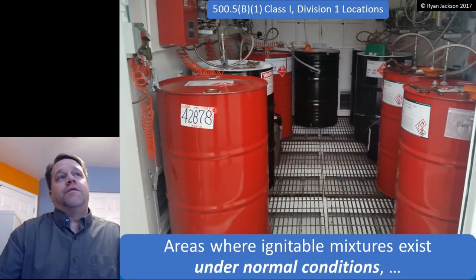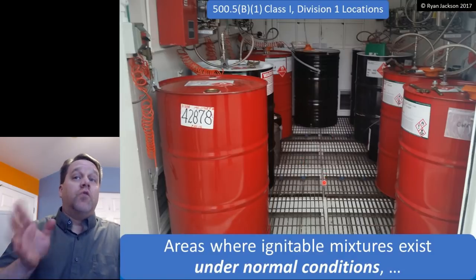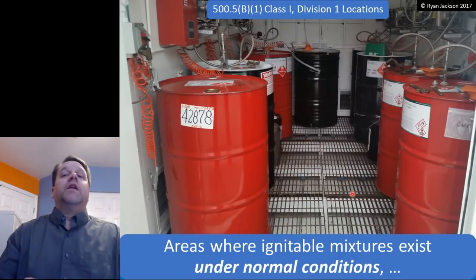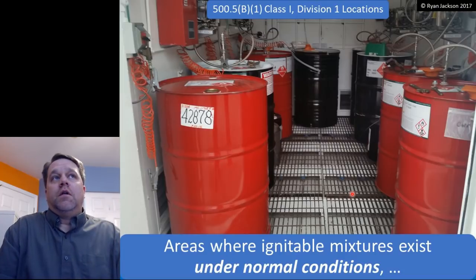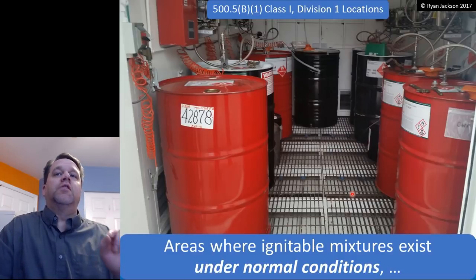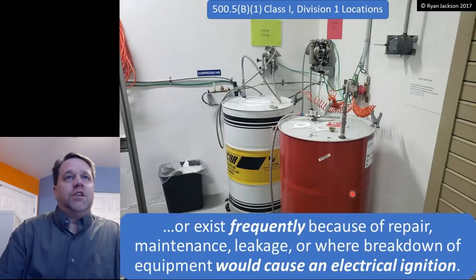We're transferring flammable liquids all over the place on a daily basis. The normal condition is an ignitable mixture. In other words, if I walk into that room smoking a cigarette, it blows up. It takes one bad thing to happen to have an incident in a Class 1 Division 1 location, because the hazard exists under normal conditions. That's a Class 1 Division 1 location.